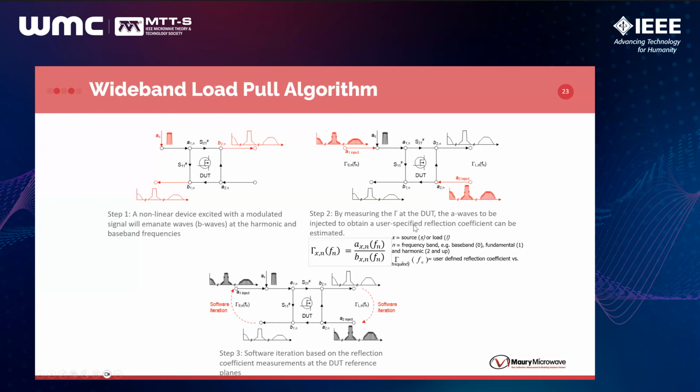In other words, we could, for example, decide to have one fixed impedance, one dot on the Smith chart for the whole bandwidth, or we can have a profile of an impedance. Imagine we have an antenna: we can measure the antenna and synthesize its gamma, the impedance of the antenna, directly on this instrument to present that load exactly to the DUT.